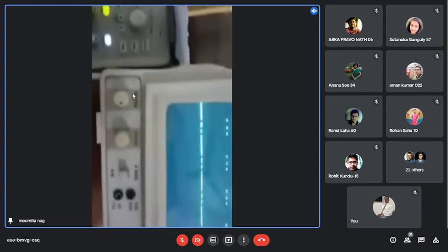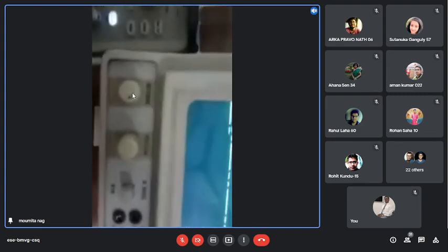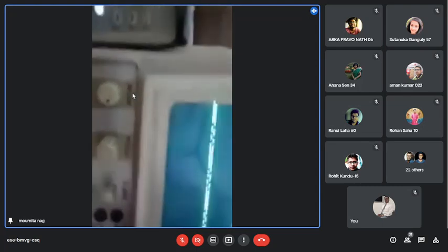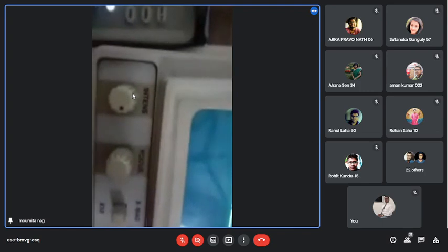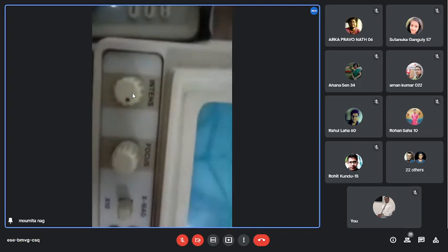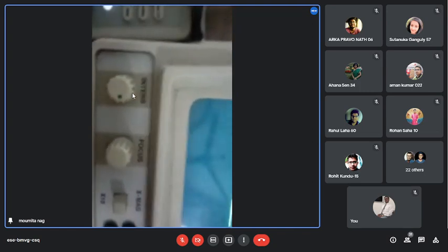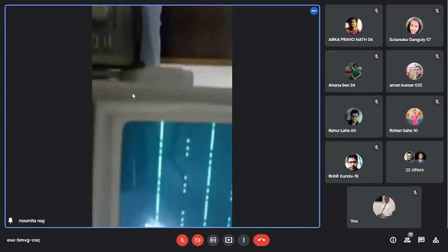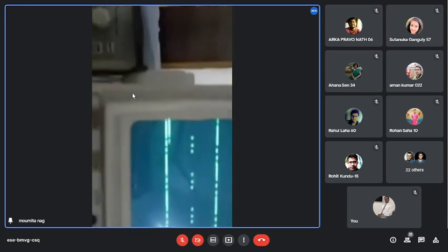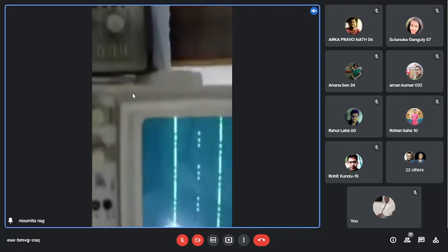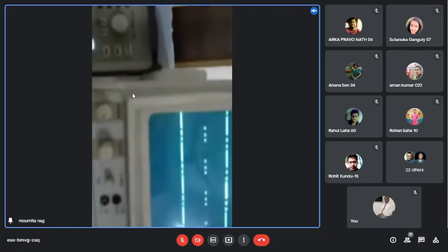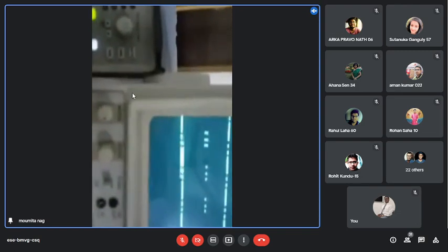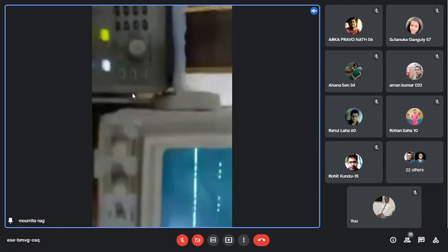You can see the T on times are the same, 0.4 millisecond, for all of them, and the T off times are different. So the positions of the pulses are changing according to the modulating signal.